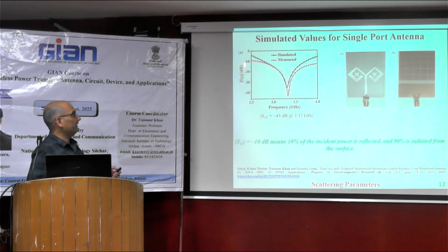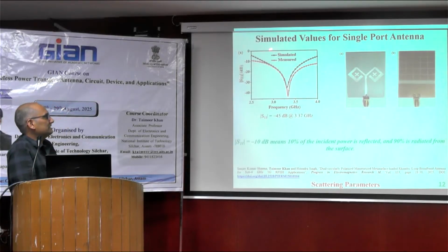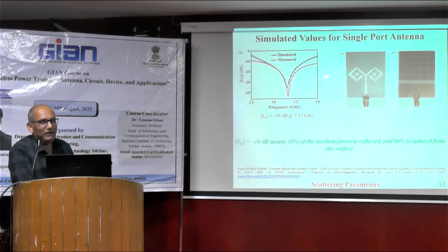In this way, the simulated and measured performance that you are seeing here is part of a paper that I have just plotted here, to give you a sense of S parameters, that S11 is the reflection coefficient. Always remember that if you are representing S11 on the y-axis in dB with negative values, it is the reflection coefficient. But sometimes in locally published papers or non-authentic references, you will see that marked as return loss. Return loss has a different meaning from the reflection coefficient. Return loss in negative values has no meaning.